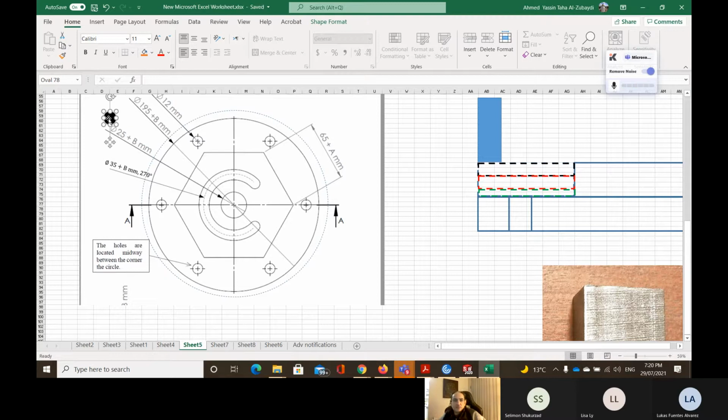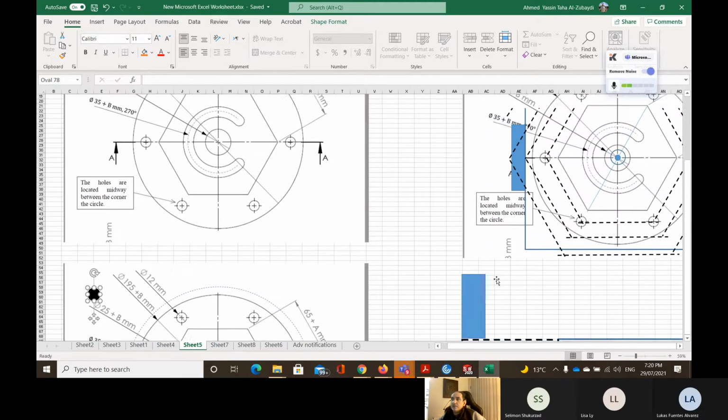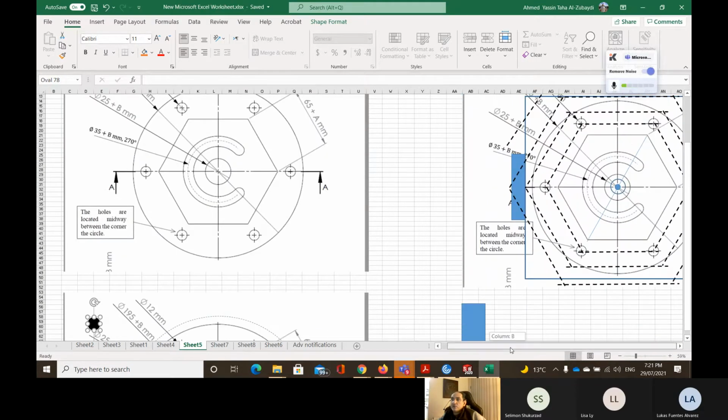This will be the setup number 2. Or this can be setup number 2. You can have 2 other setups. The one in the middle: when you finish the cutting of the top, take the part and put it on the inspection table and take a look at it. Take some measurements to be sure that the dimensions you had are correct.